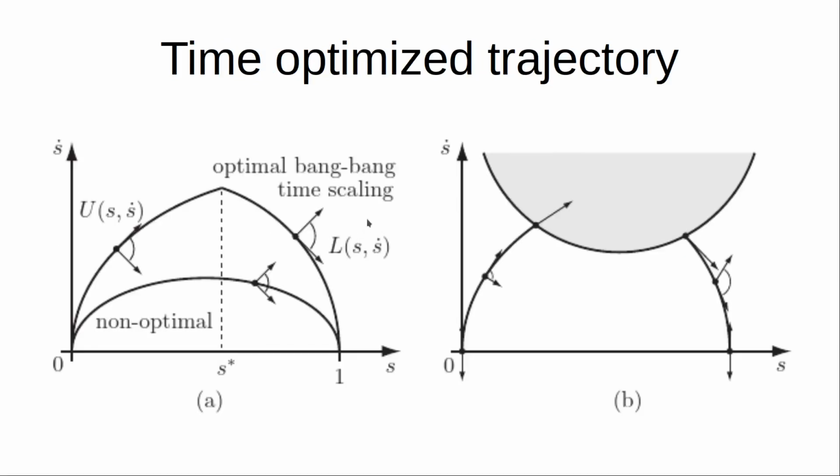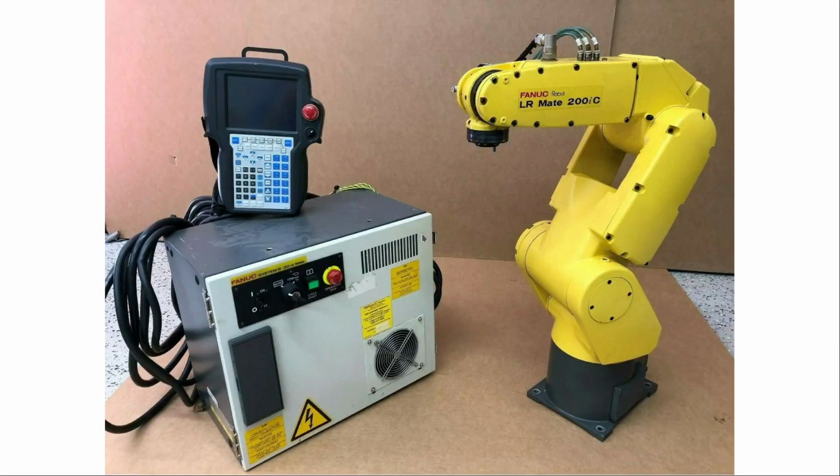And this is the time optimized trajectory generation, the common illustration for it. You can see it's very nonlinear, and it depends on the upper and lower limits of the dynamic model, which means the overall trajectory generated by these industrial robot arms are very complex and basically not possible to reverse engineer and hand calculate a trajectory duration out of the start and end location.